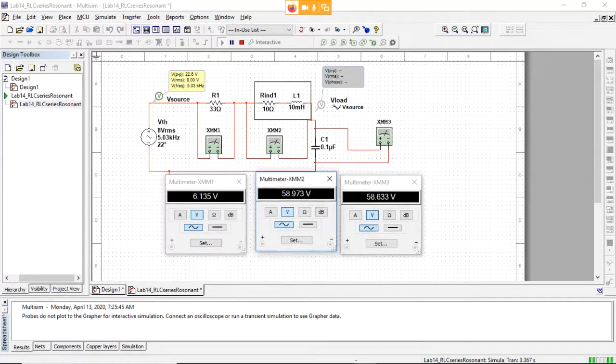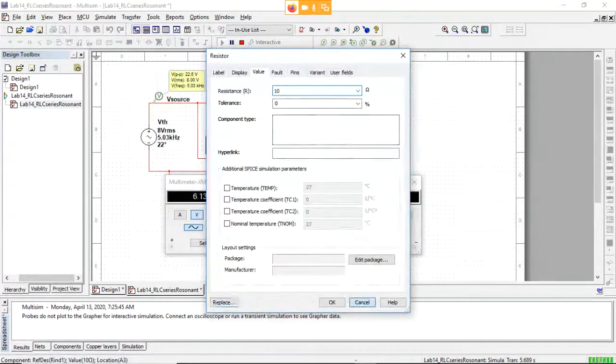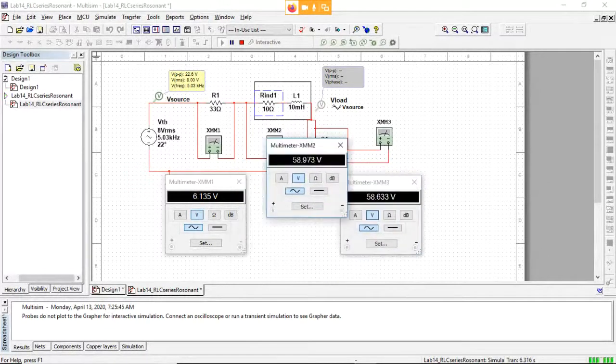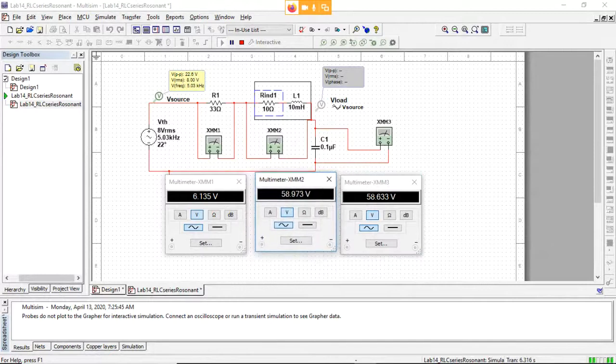between the inductor and the capacitor here, because these guys are sitting here playing hot potato and there's very little resistance, right? We dropped that resistance from 200 down to 33, but actually it dropped from 230 down to 40, because there's 10 ohms here. But you see this hot potato thing going on here. This is a pretty active hot potato game.